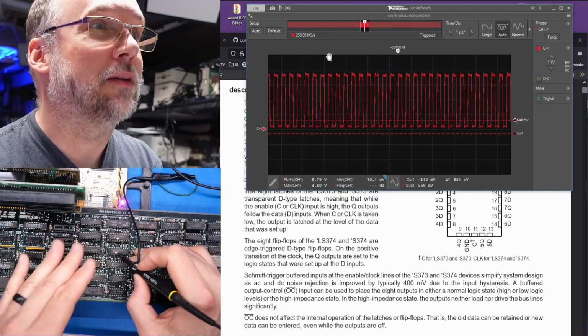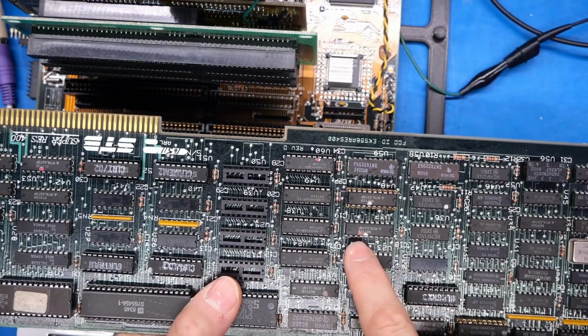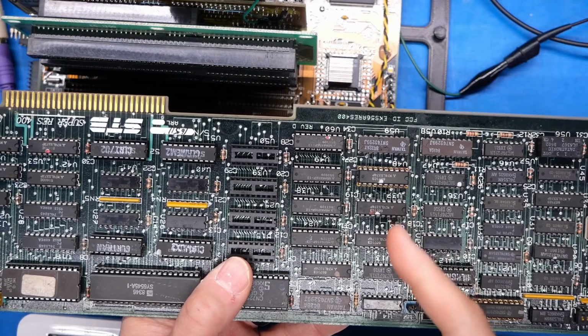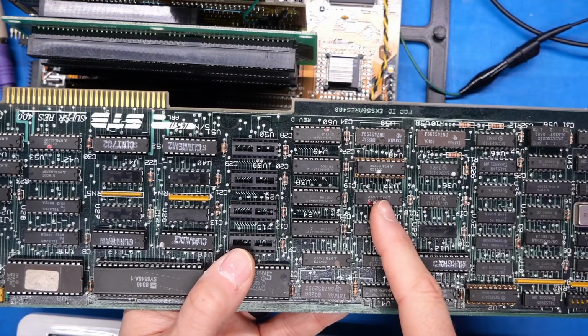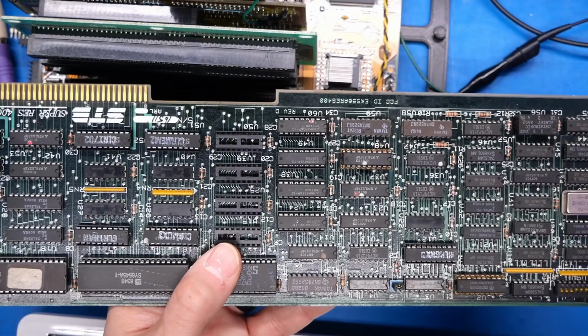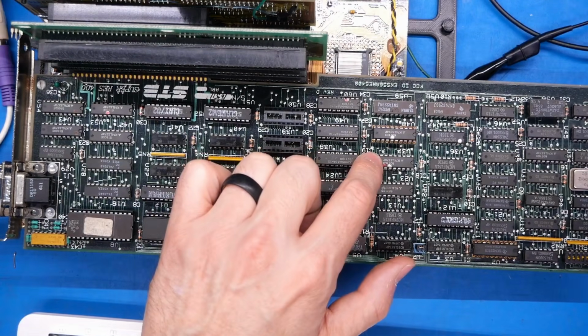So it's got to be this chip that's bad. I think the issue is somehow the clock is leaking through to the output on this flip-flop. So it's not just a dead output, but it's leaking through. And the overlaid clock somehow causes this chip, which handles the attributes, to always just not have the red. So I just put that pin back in over here, and I'm going to socket this chip now.